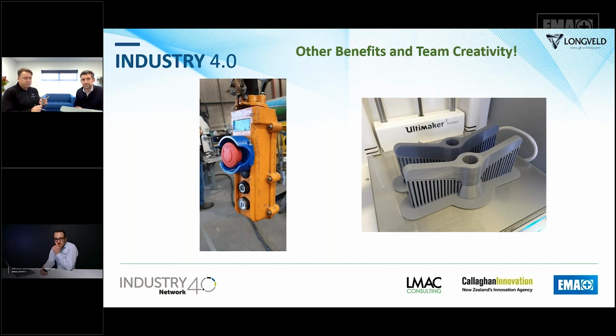Like we had this mixer blade here before, and the customer couldn't deliver us a few more for the other equipment. So what we did, we 3D scanned it in-house. After that, we tweaked the model and we 3D printed the actual part for investment casting. With that, we got back another part, a clone. So now we can 3D print and cast as many parts as we need without needing the supplier.